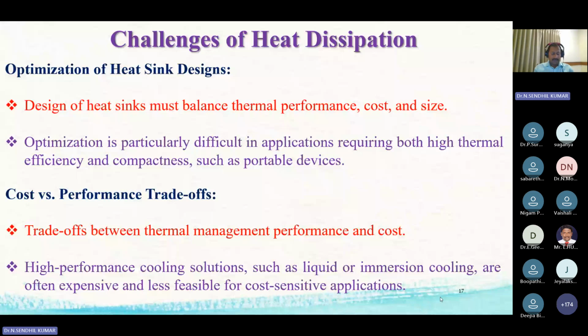Such things, even for portable devices, compactness also, we have to increase. That is, we have to design the heat sinks. Numerically, we have to design, and then we have to check in the things experimentally, we can do that. So that optimization is very, very important, where you have to place the heat sinks, how many number of fins, all those things. You have to do the simulations, and then only you have to put it. You cannot just like that. You have to design it properly.